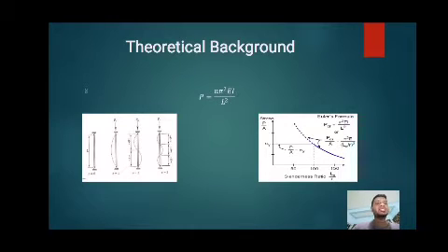The second picture is the stress versus slenderness ratio graph. When the slenderness ratio for a material with some buckling stress is more than the acceptable slenderness ratio, the Euler's formula can be used. Yet if the slenderness ratio is lesser, the Euler formula is invalid.